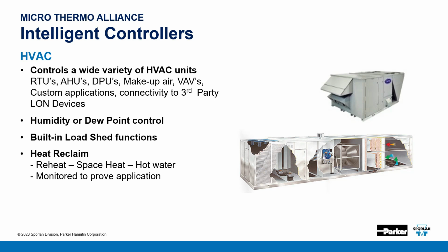Microthermo smart nodes can also control HVAC units. Some manufacturers, like Seasons 4, actually use Microthermo smart nodes within their equipment. But as long as the rooftop unit has a true Echelon chip on board, we can integrate that unit so that you could interrogate, visualize, and troubleshoot that HVAC unit right through the Microthermo front end.